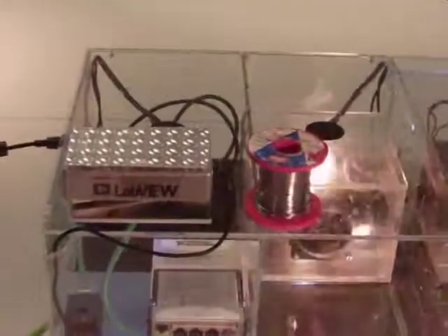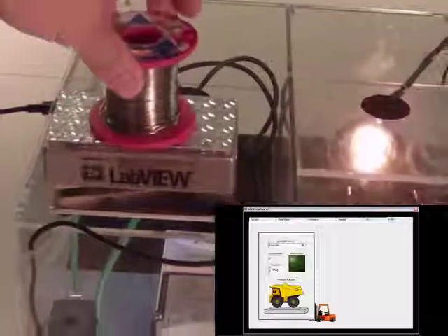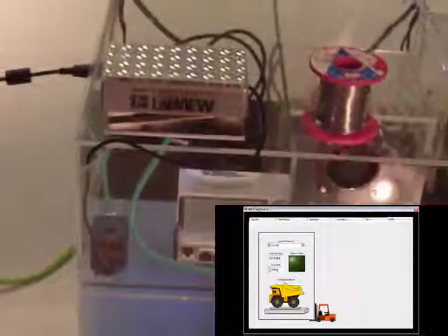We used a DAQmx driver and a USB data acquisition device, which included a C-series module. This C-series module was designed for load cell measurements. This measurement could have also been added to the cRIO, however this shows the tight integration between the different platforms.